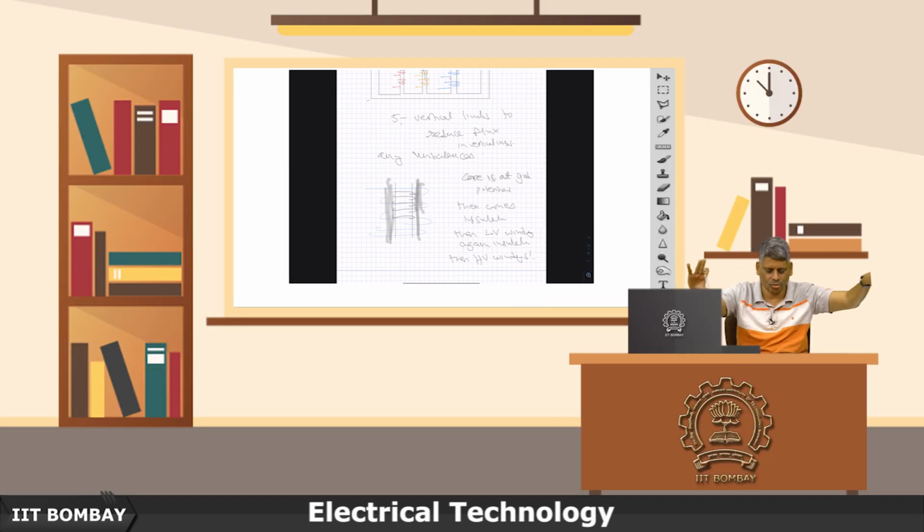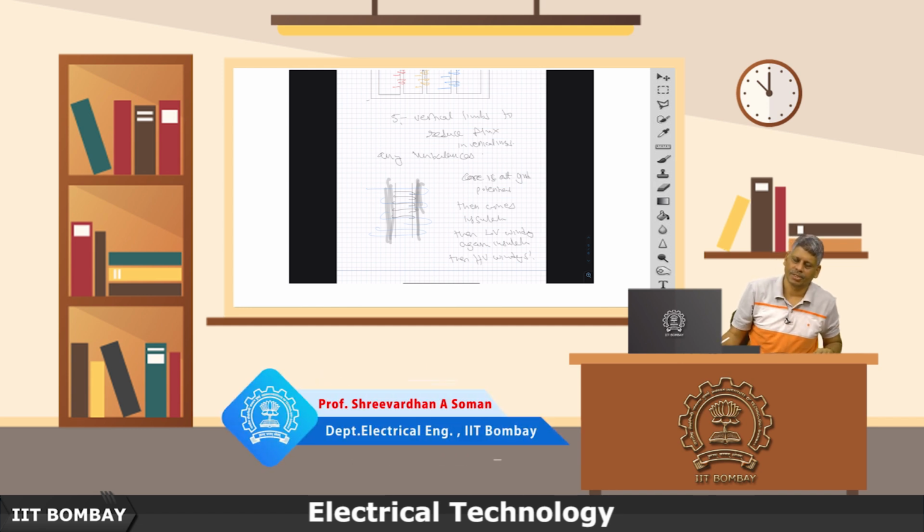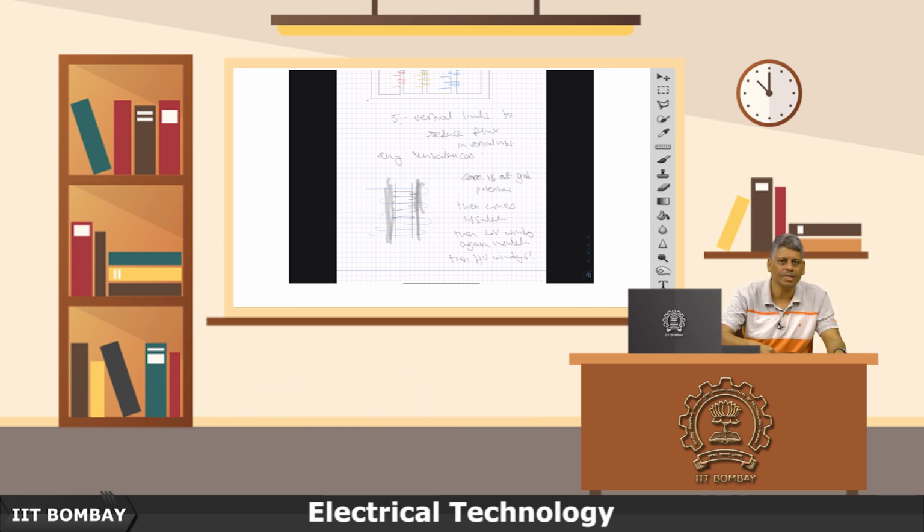So the insulation gets properly designed, and it is not necessary that the LV winding should come first and then the HV winding should come below. It can be like this is the core, first I have a LV winding, then some insulation, then I have a HV winding also around it. There are a lot of innovations that can happen in the construction, and we can only peep here and there a bit into it, and we will stop here for now.